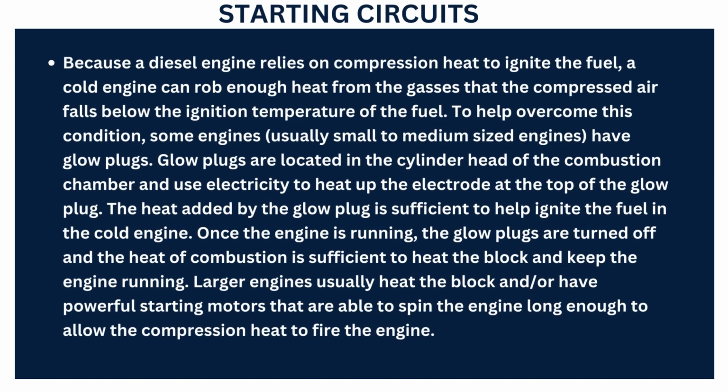Because the diesel engine relies on compression heat to ignite the fuel, a cold engine can rob enough heat from the gases that the compressed air falls below the ignition temperature of the fuel. To overcome this condition, some engines have glow plugs. The heat added by the glow plug is generally sufficient to help ignite the fuel in the cold engine.